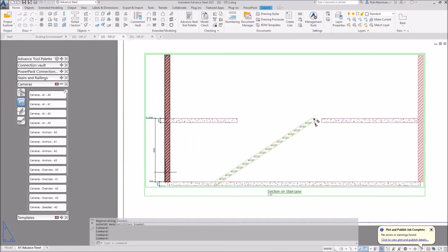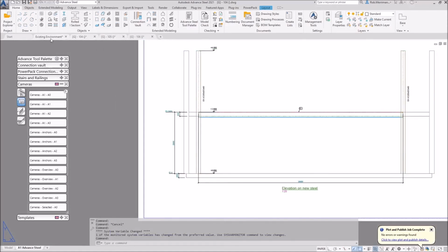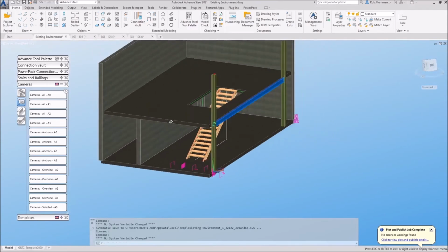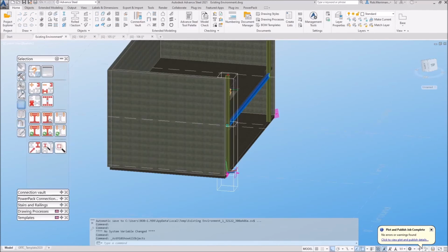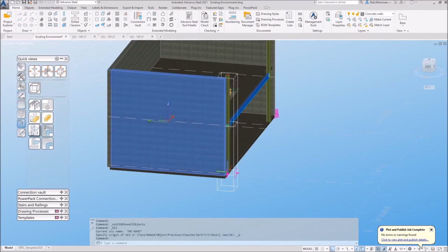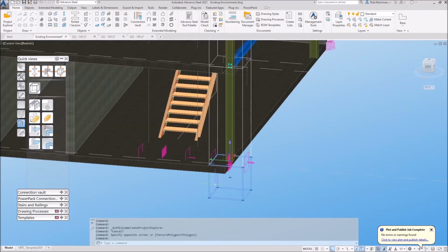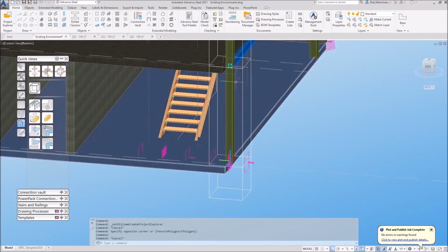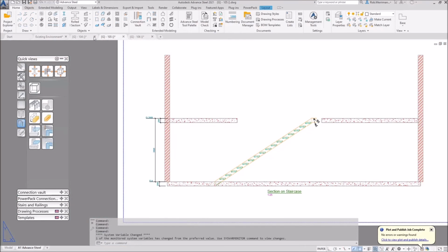Now you'll notice in here I don't have any level markers like I do on this elevation here. That is because, I'll just set my UCS back to world and turn everything on. We'll just get rid of that wall. When we create the levels within the Project Explorer, what the system does is it creates these little model view boxes. Because the camera is slicing through the model view box, it will pick up the level. You see, with this camera here, it's not actually touching any of these model view boxes, so therefore it's not going to give me the level markers.